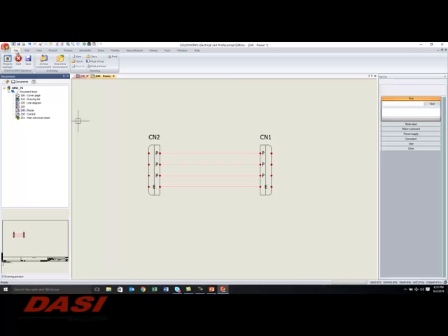The way the software is set up is that you have communication to libraries, which are all handled through the SQL database. That database allows you to have a number of different things. It has title blocks, it has project templates, it has your symbols, it has your manufacturer's data. All of that information is in the SQL. With our schematic package, that data can be put on a server that can be shared among multiple users. Standard keeps it on one local system. You don't share it with anybody. It is yours and yours only.